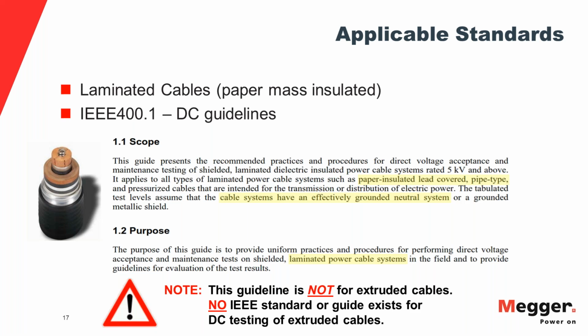And the question was, is this applicable for solid dielectric cables? And as it was found by the scientists, no, it is not. The DC testing is actually damaging the solid dielectric insulation, EPR and XLPE. So this is why it's not recognized anymore, not in IEC and not in IEEE. There is no DC test standard for years now.